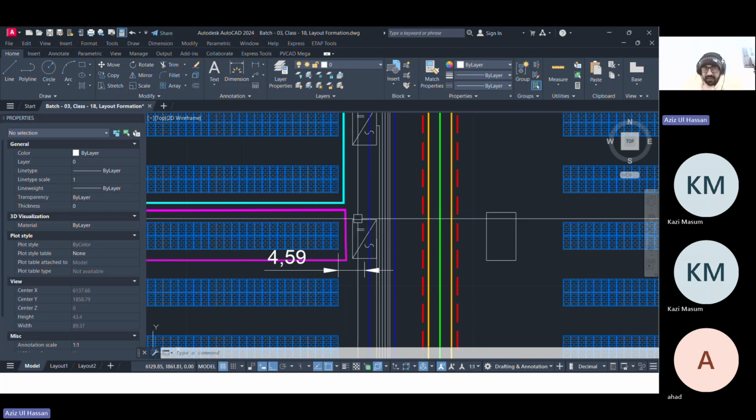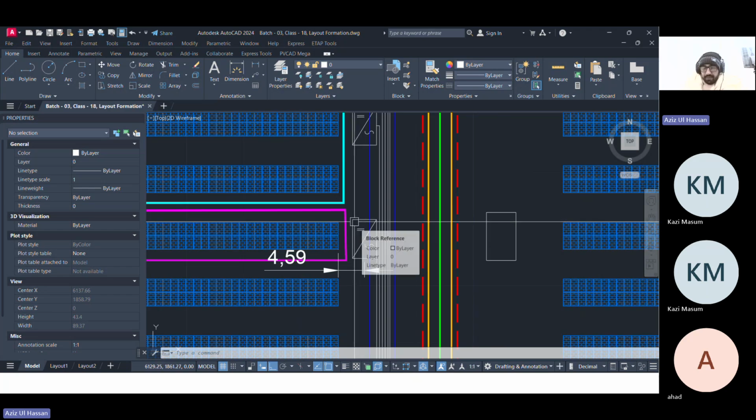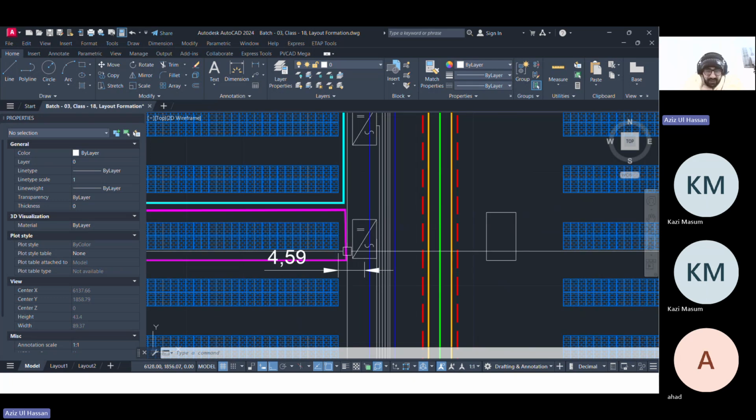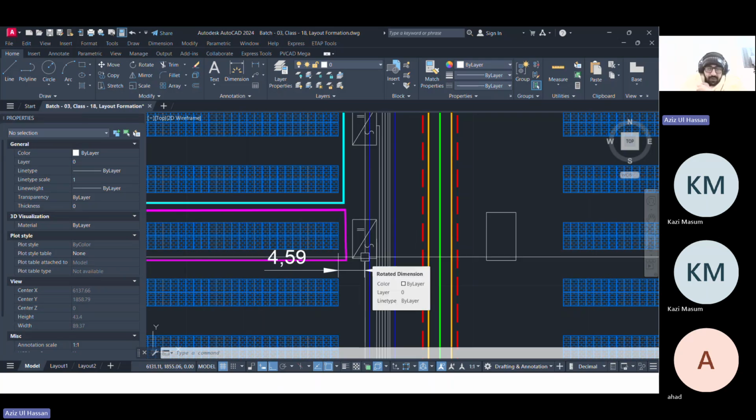When you get the length and you prepare the BOQ, the cable sizing, the cable schedules, they are wrong. When the site team follows your cable schedules, their lengths are not okay, and they will cut the cables. So that is why at the end of the project, your cable will be short. So that is why we have to give the proper coordinates of the inverter on site.